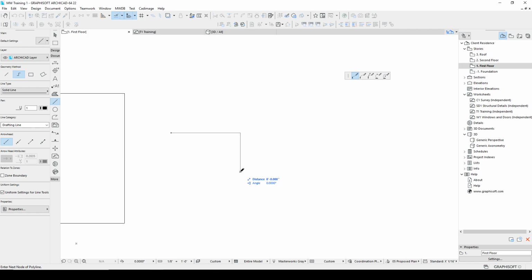The only advantage of this is that instead of waiting for the guidelines to show up, or having it fall on and off the guideline, I can force it onto the guideline. If I hold Shift and type a number, it's not going to work. I have to hold Shift, then hit R, and then I can release that, and then I can hit 10. Now, you're going to struggle with that for a little bit,